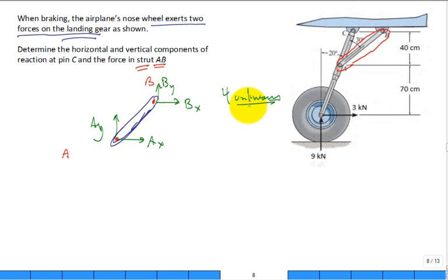But if you did a little analysis, when you did the sum of the forces in X, you would conclude that AX plus BX is equal to 0. True? So it's like I just went from 4 unknowns to 3 unknowns. And likewise, the sum of the forces in Y, AY plus BY is equal to 0. Really there are not 4 unknowns for this free body diagram. They're just 2 unknowns. I'm not going to be able to solve for them.